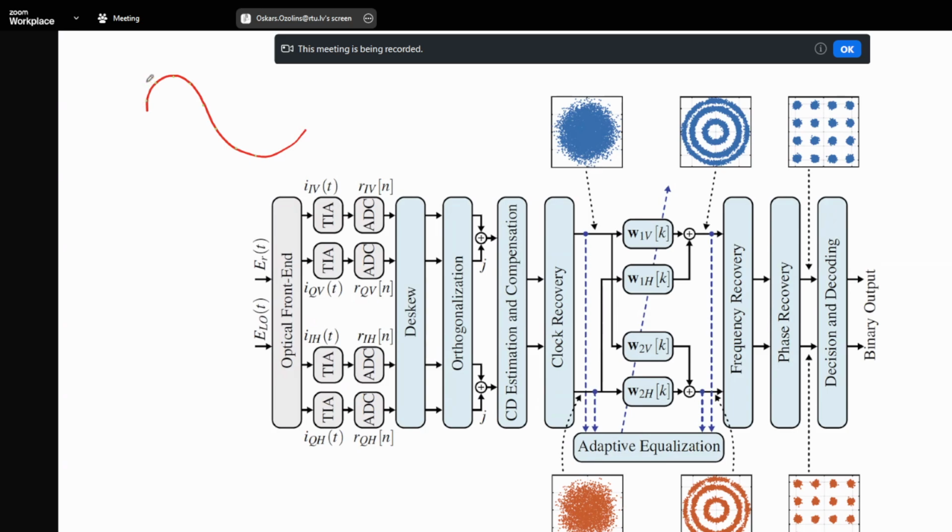And here we assume that, well, this is our axis, so this is the start of the signal. But in practical systems, we don't know when we are going to start to sample. So we need to find at least the closest sample to the sampling instant, and also try to match where the symbol is starting.